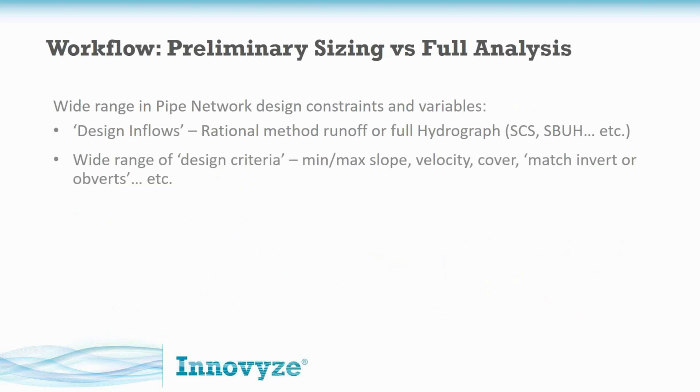From there, there's a whole range of criteria that engineers use on a regular basis. Depending on your site, depending on where you are in the country, there are a range of different items like setting the elevations for a pipe network to accommodate a minimum velocity, let's say, to ensure that dirt and debris is scoured out, and the system doesn't fill up.